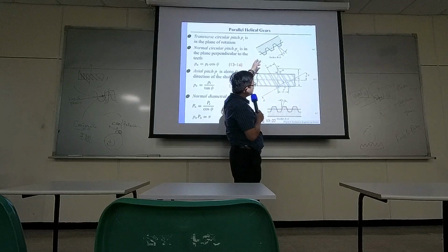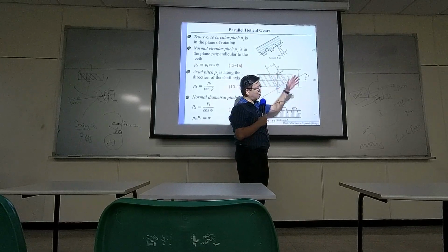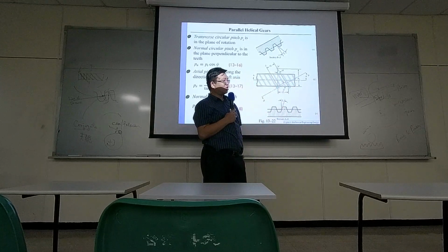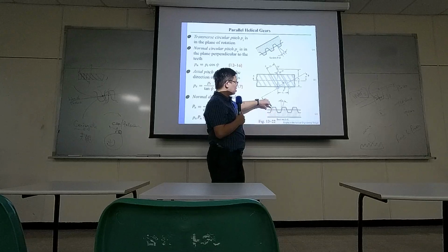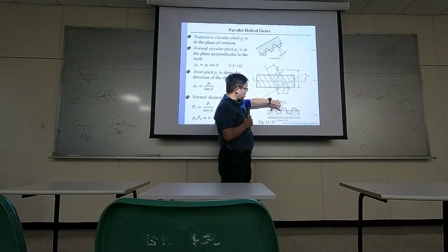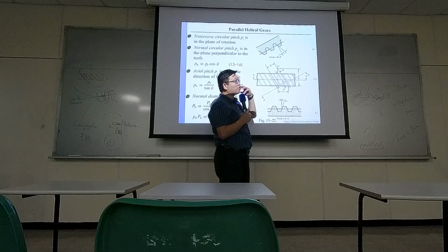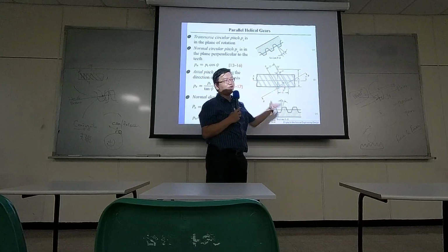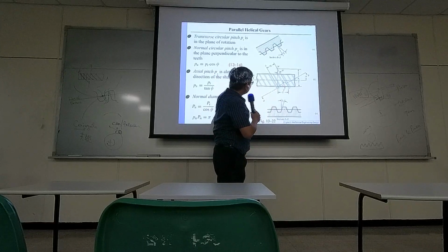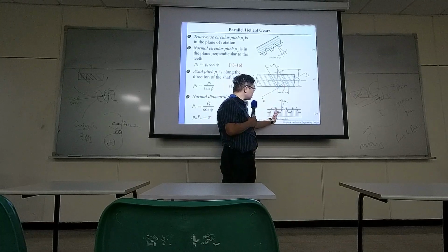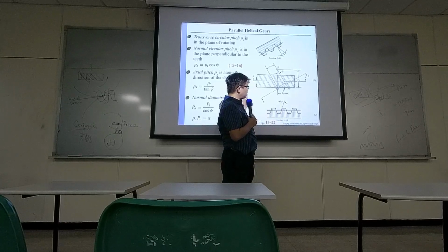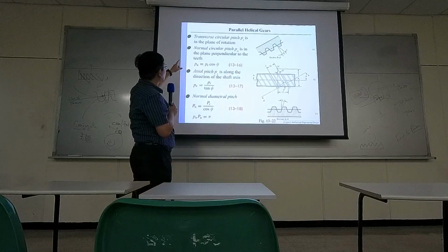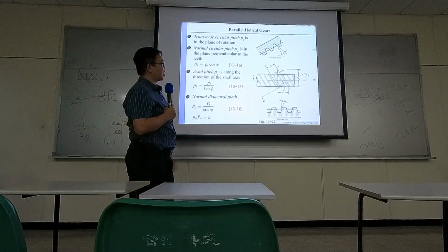So when you take a walk along the tooth profile in different directions, you see different periodic distances. So they compute the pitch along different directions. If you compute the pitch along this transverse direction, they call it PT. T represents transverse, like horizontal.